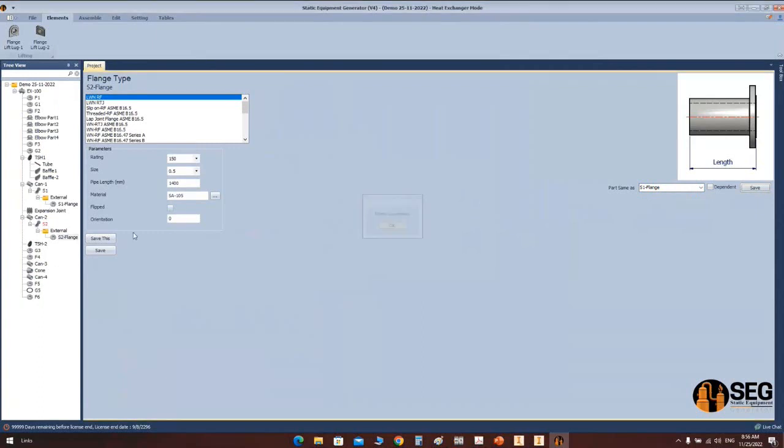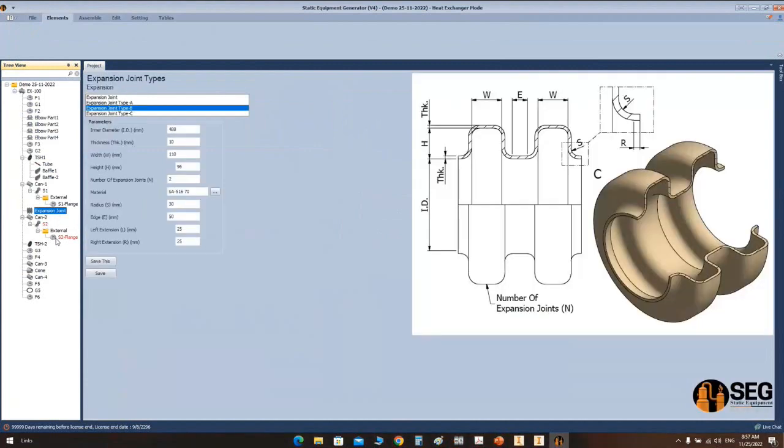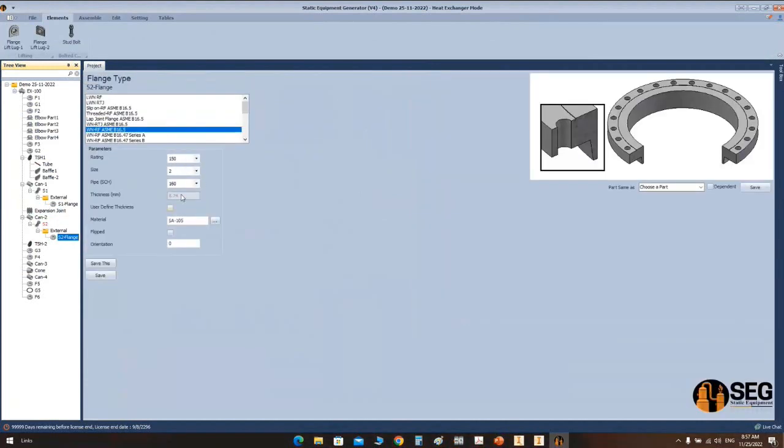Automatically, you will get saved successfully. If you would like to review it, kindly go to another point and make a refresh. Here, that's it. It's a welding neck raised face flange according to ASME B16.5. The same rating, the same size, same schedule, same material, all information. Now, if we make a run for the nozzle,